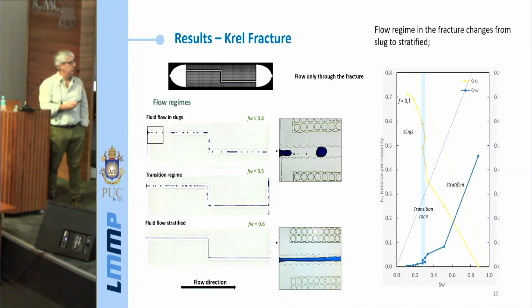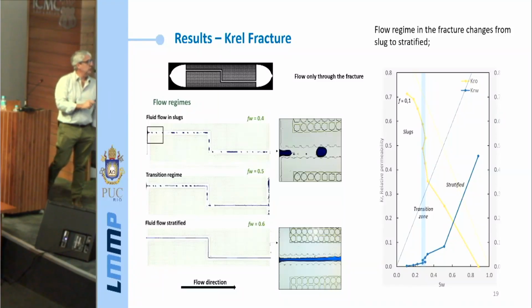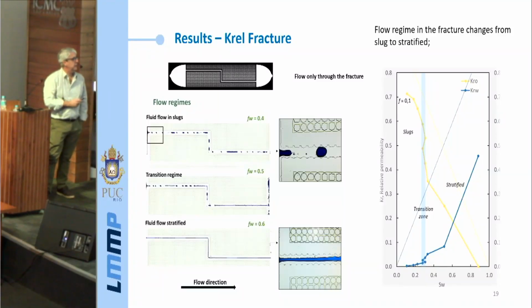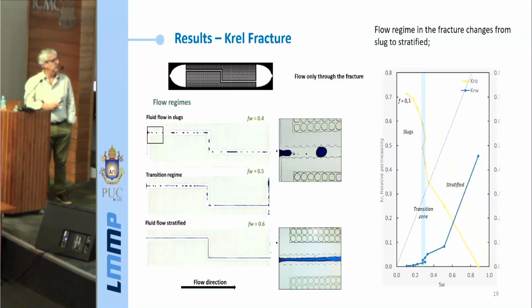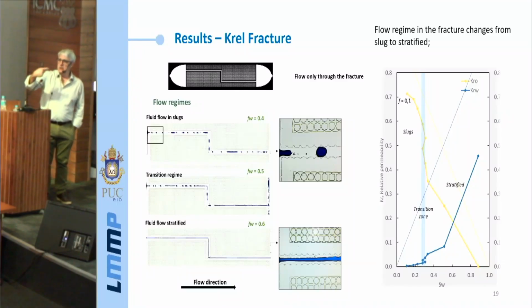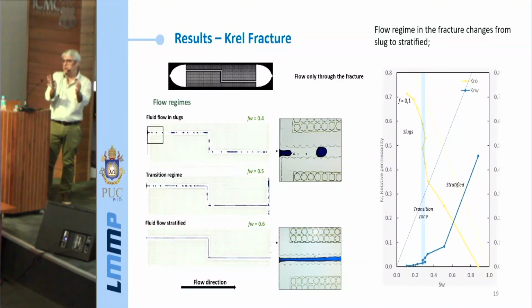understand pore scale flow. In the literature, 99.9% of the research that's done in this area assumes that the flow resistance, or the relative permeability curve of the water and the oil phase, is a linear function of the saturation. Because if you have a pipe and if you have liquids flowing in slug, that's what you're going to get if you work the Poiseuille equation on that, okay?